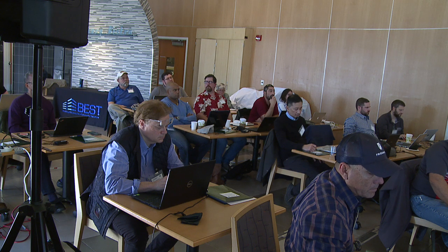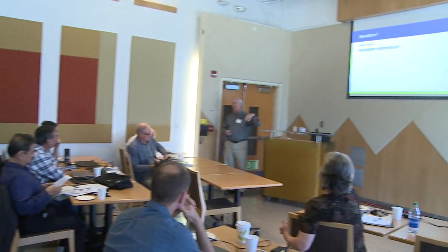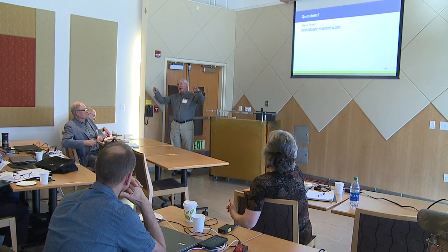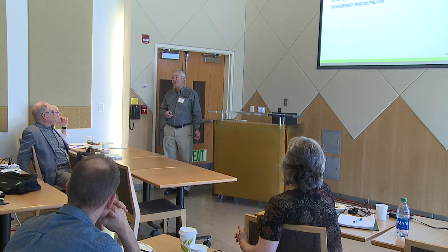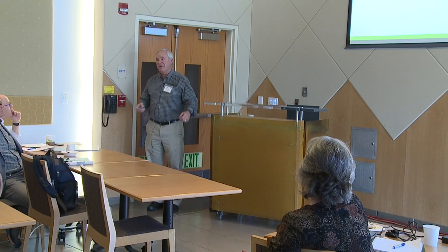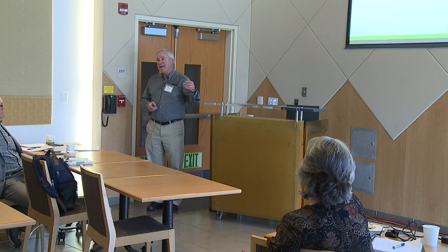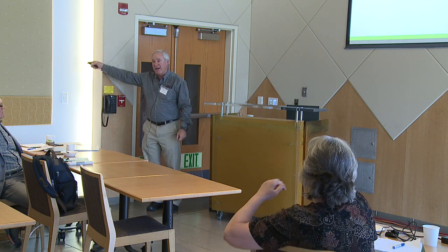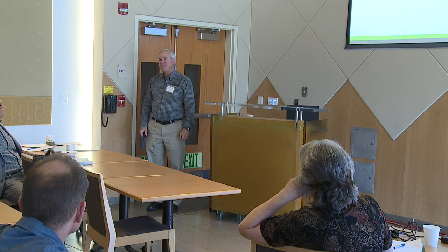Well, the trim and respond is based on request. So a zone that needs more static, when their damper's almost all the way open, will say, I want more static. And the zones that are down lower, they're not going to generate any requests at all. So they're perfectly happy. And so only the ones that are the critical zones are going to have requests. But if you saw from that screenshot I have, which is a real job, the number of requesters was almost every zone at some point in the day. The sun's over here, these guys are requesting. The sun's over there, those guys are requesting. In the wintertime, it's the interior zones that are requesting. So it spreads itself around.